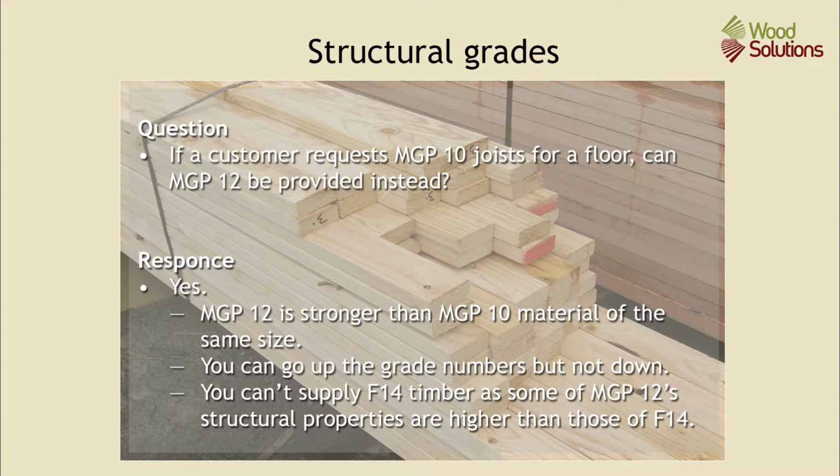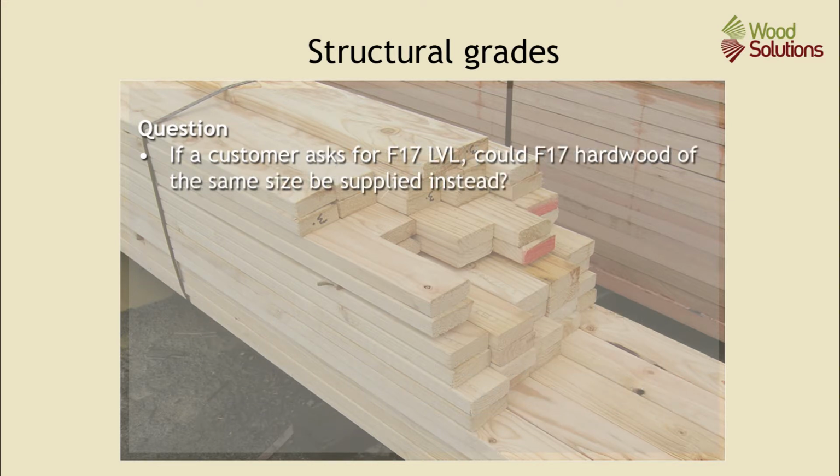They could even be supplied MGP 15. However, you can't supply F14 timber because some of the structural properties provided by MGP 12 are higher than those provided by F14. If a customer asks for F17 LVL, could F17 hardwood of the same size be supplied instead?